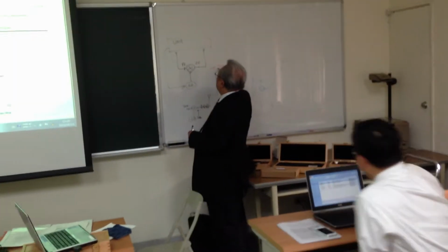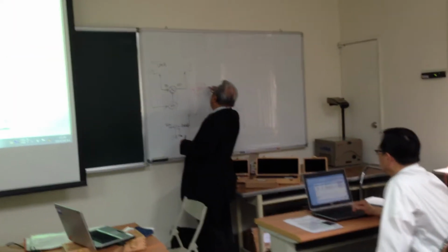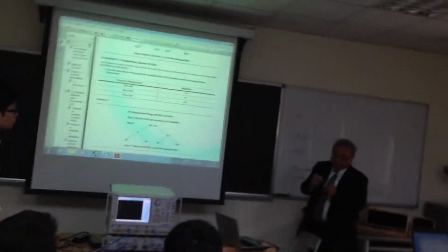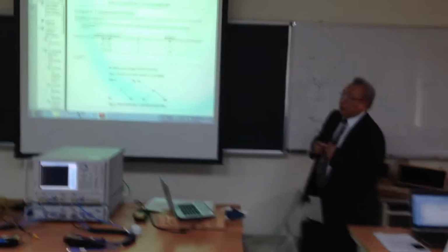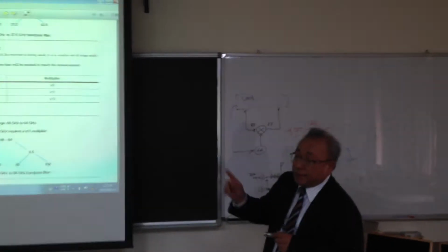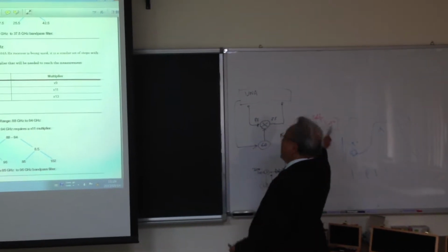Save it to the text file, then we have to modify it to the S2P file, because the noise figure measurement can load an S2P file for DUT gain data. So we have to convert here.